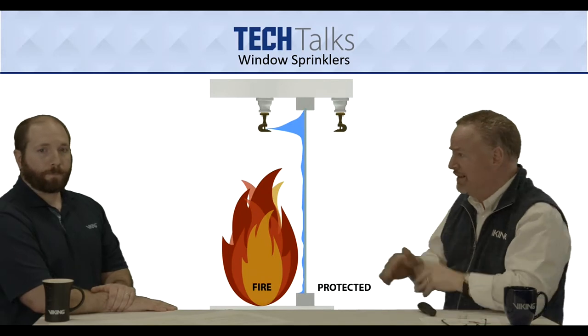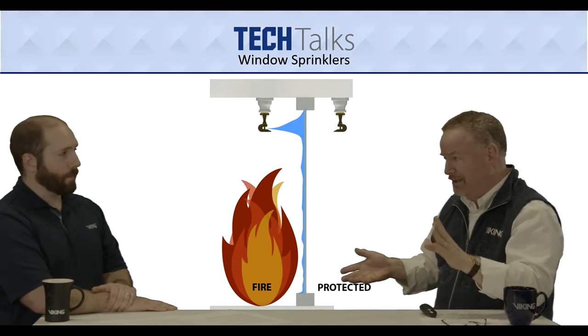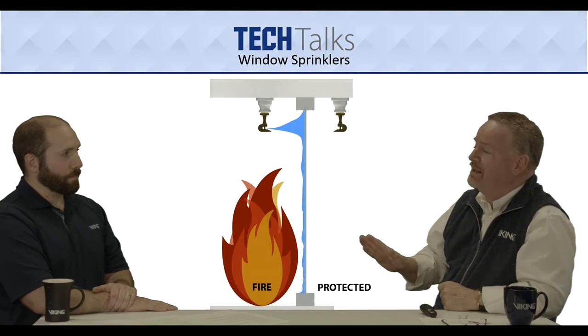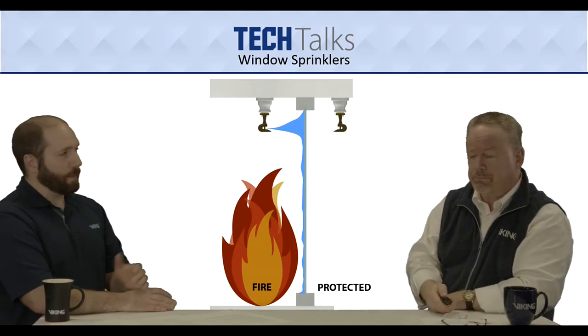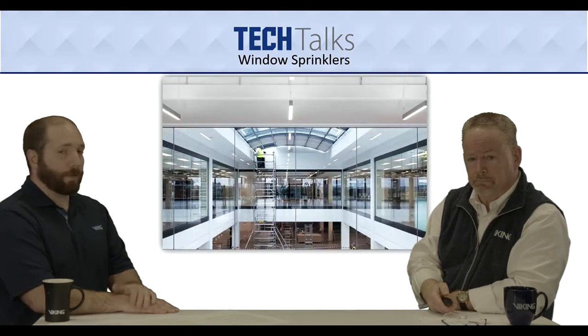Yep. But here's what we were talking about here. This sprinkler is not designed to spray any water on the fire. That's the job of the ceiling sprinklers. This one is intended to spray and maintain the integrity of glass in a fire rated separation, right? Correct. Okay. Yep. Basically, the sprinkler provides that fire rating equivalency.